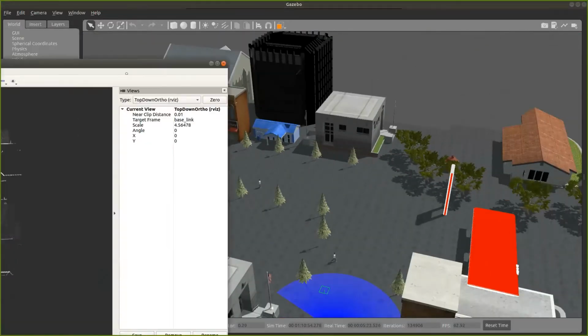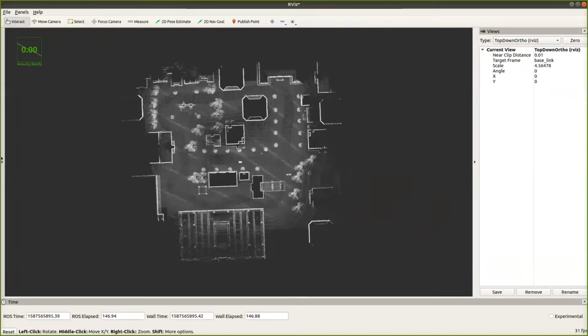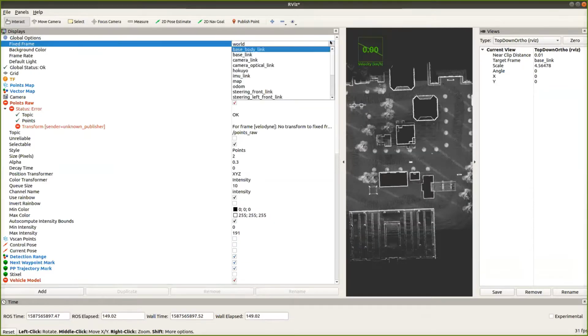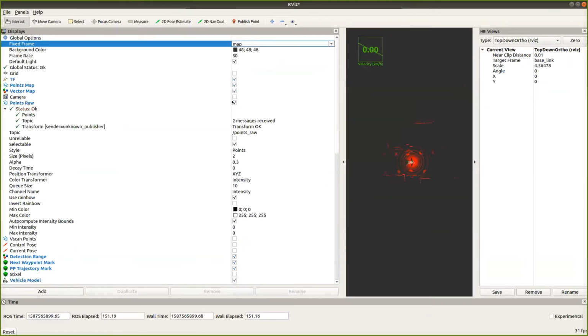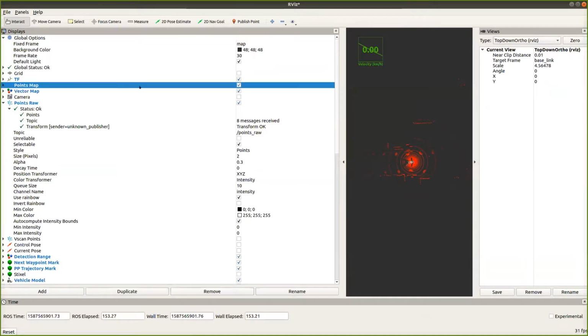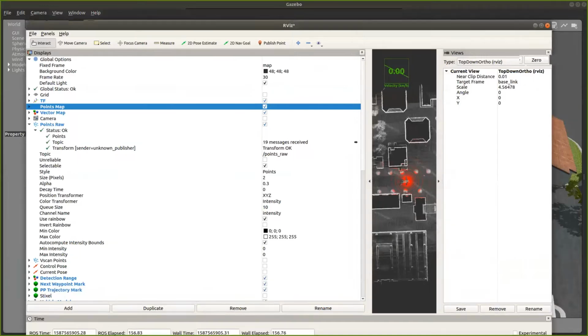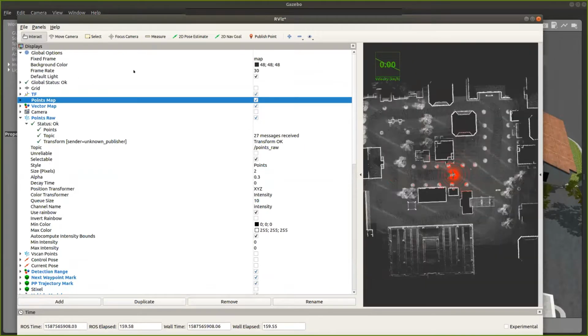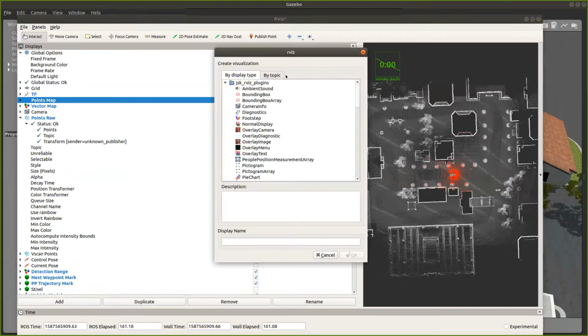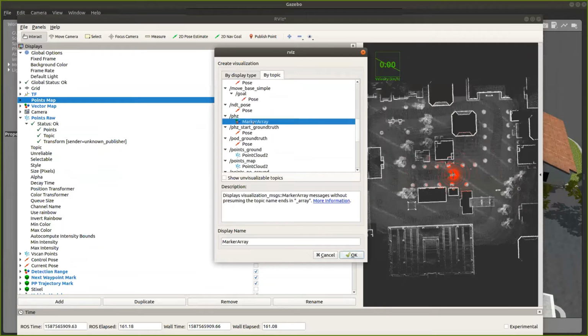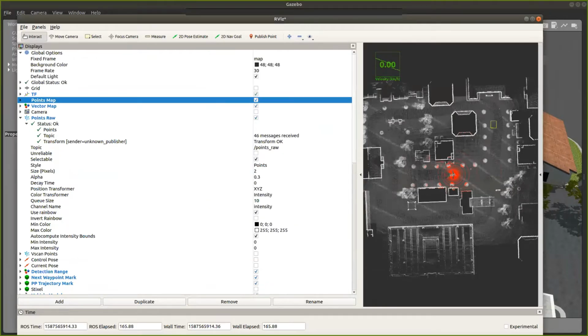We've also loaded the Gazebo world point cloud map into Rviz. Next, we'll be starting the Autoware localization and planning nodes. The red circles that you can see on the map are the point clouds that will be used by the localizer. And you'll see a yellow box appear on the screen, which will represent the payload handling zone, which has been obtained from the prior estimate of the pod available to the system.